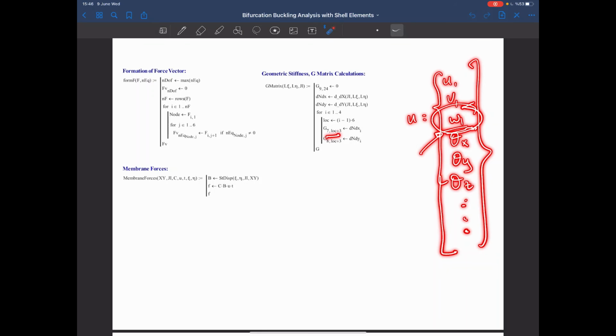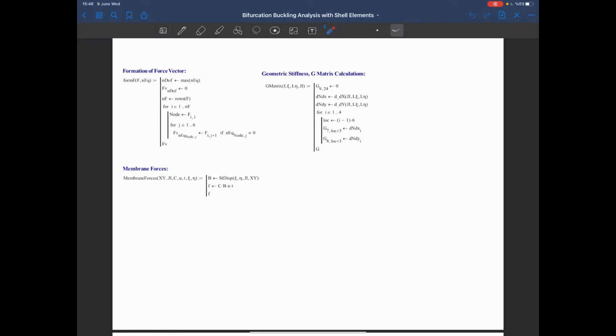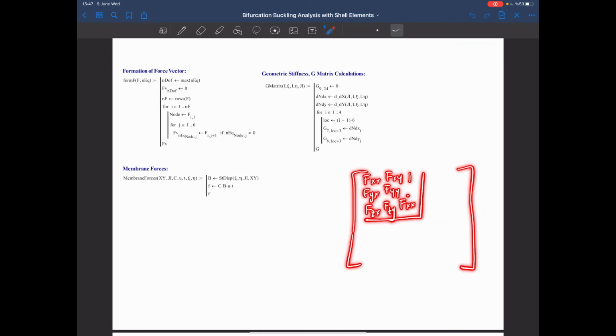So that's why I'm just putting the derivatives to the third, ninth, and so on to these columns. Now row wise it's 7 and 8 because the force matrix that I will create is as follows: fxx, fyy, fzz, fxy, fyx. So we have the fzx, fzy, and so on, the same here. So again, another 3 by 3, another 3 by 3 here. Okay, so that will be the full stiffness stress matrix for the whole shell element.